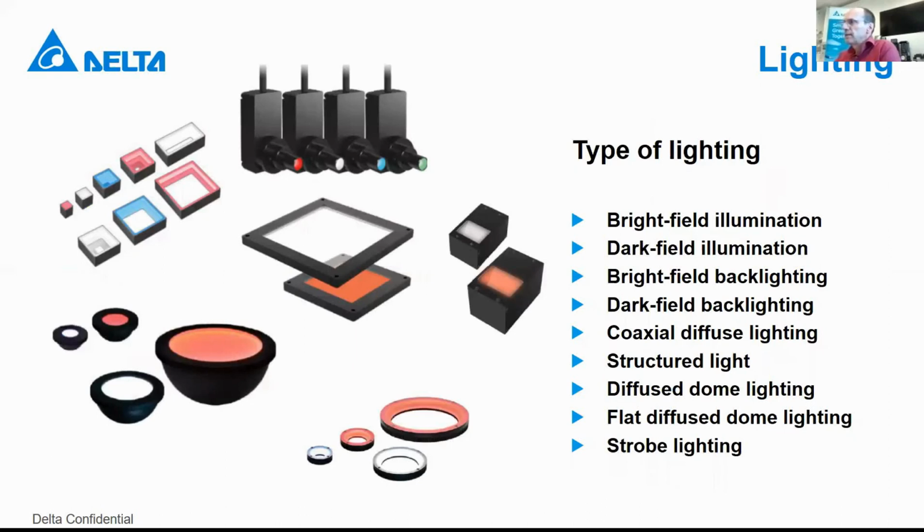What kind of lighting do we have? Of course, you see here already a lot of different types. We have bright field, dark field, backlighting, coaxial lighting, structural light, diffused light. Of course, you can use a dome, but you also have a flat diffused dome. You have different kinds of light sources, and depending on what you want to see, you choose the light source itself.